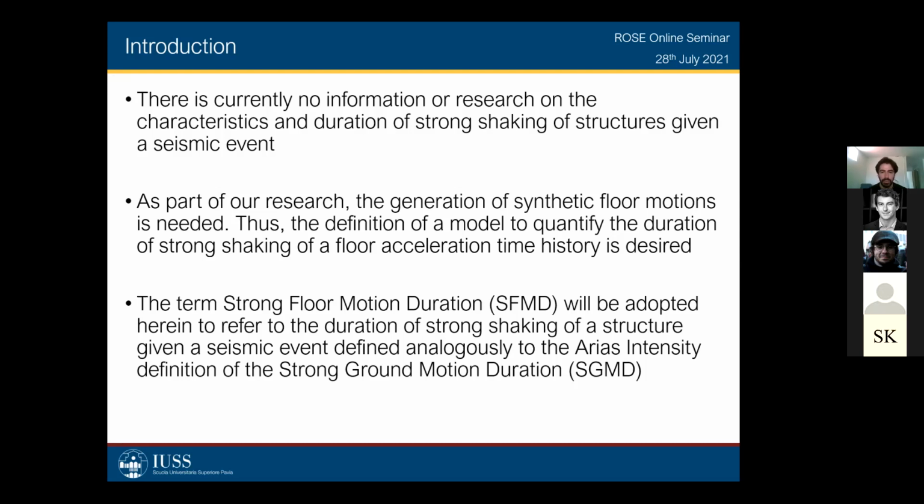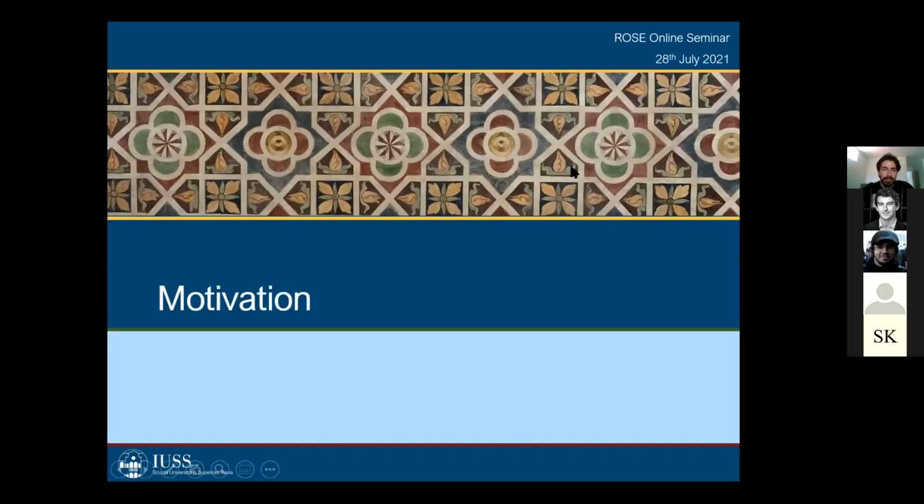The term strong floor motion duration, with the abbreviation SFMD, will be adopted herein to refer to the duration of strong shaking of a structure given a seismic event, defined analogously to the Arias intensity definition of the strong ground motion duration. We're going to talk about this in more detail later.